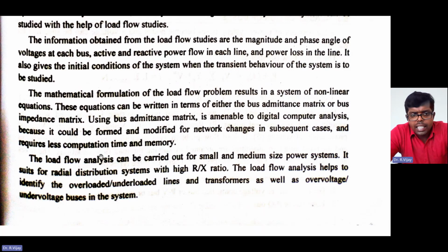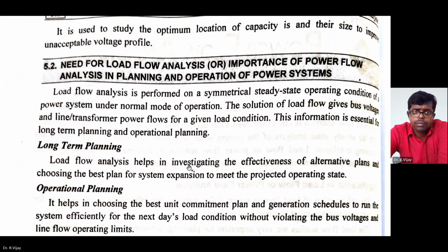Next, load flow analysis helps to identify overloaded or underloaded lines. You can easily check which bus is overloaded, which bus is underloaded, which transformer has over voltage, and which buses have under voltage in the system. Like that, you can easily identify by using this load flow analysis.